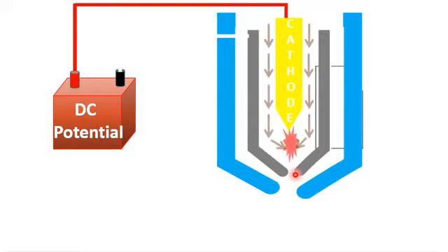This means the temperature of the directed plasma stream will reach thousands of degrees centigrade. Dear student, please note that the temperature of the plasma when it passes through the orifice usually reaches around 10,000 to 30,000 degrees centigrade.